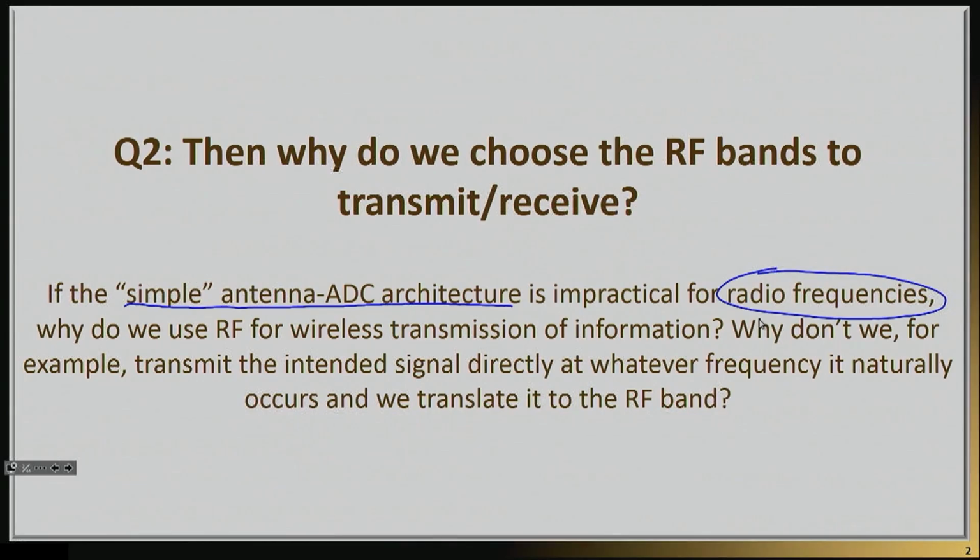One of them, for example, was that the signal that you collect is so weak that you would have to actually get a 100 dB amplifier at the input at the RF frequency to actually get the signal at the right level. And as we discussed last time, this is a big no. This is a big difficulty. We can't do that. And so the natural question that comes here is, then why on earth do you actually choose to work with RF frequencies? Why don't you do something else?